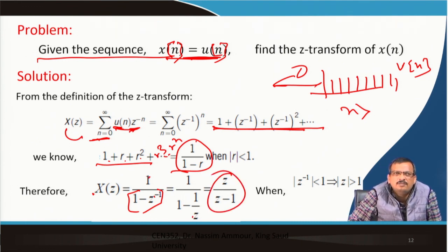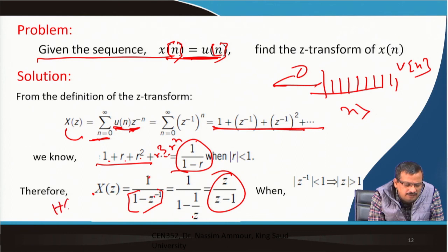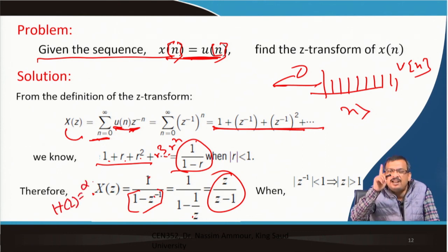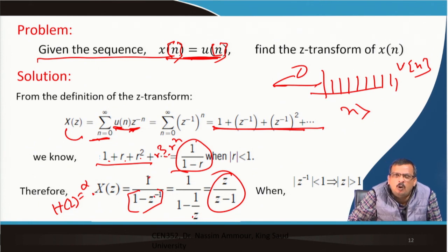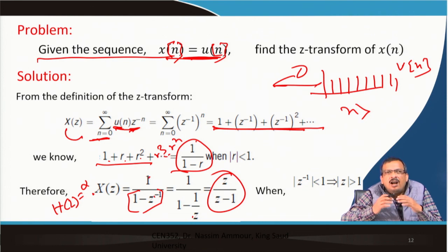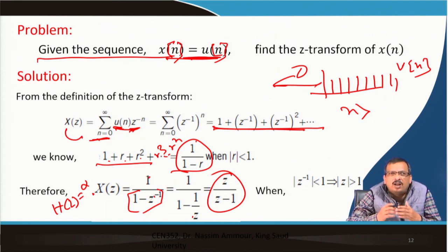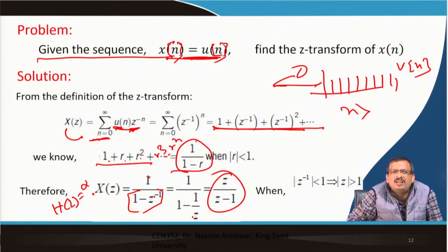Then what is the ROC? Region of convergence, for which X(z) is not infinite. Here is another point. For every pole, X(z) is infinite. So, that is why the poles are not within the region of convergence of the Z transform. Poles are outside of the region, or I can say the poles are not included inside the ROC.